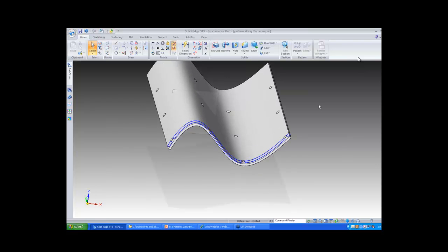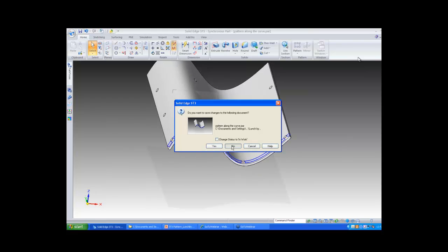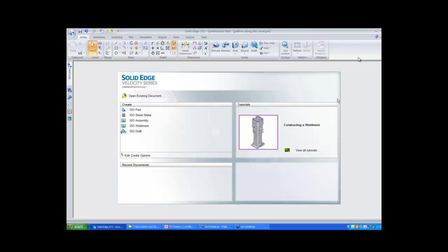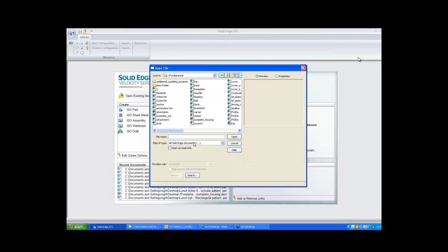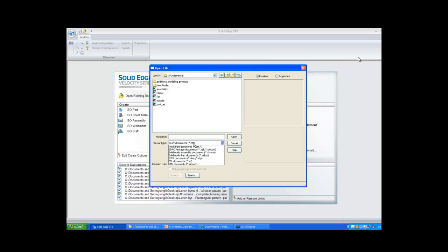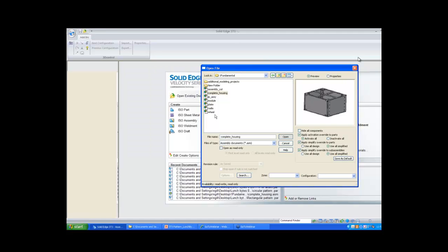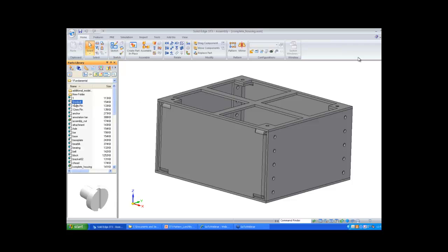Now, suppose you have an assembly. Do assemblies have patterns? Yes, assemblies do have patterns, and in case of creating patterns inside of assemblies, you need to have some parts. So I'll just open an assembly here, and from my parts library, I'm going to use this part and line this bolt on this hole. So I just select the cylinder face and the two faces to line up.